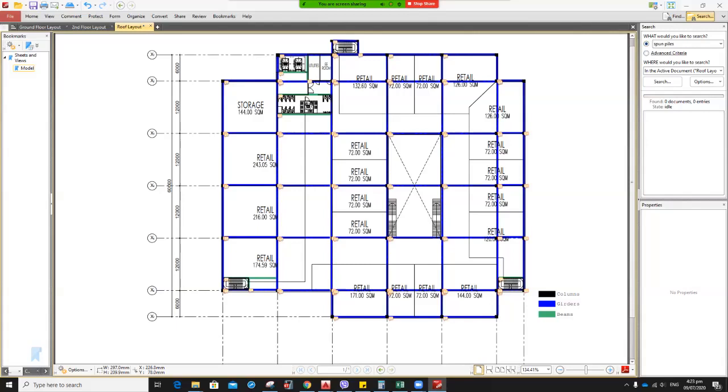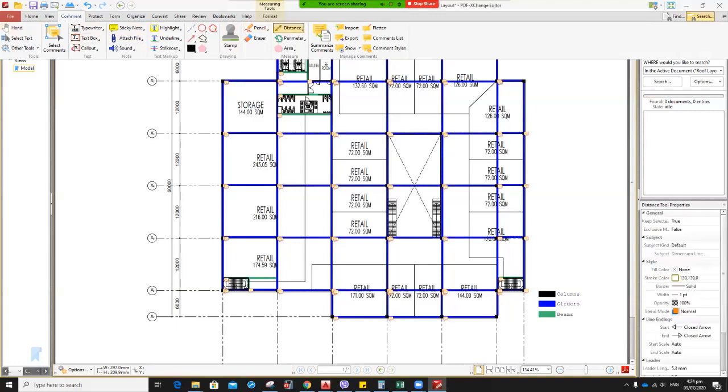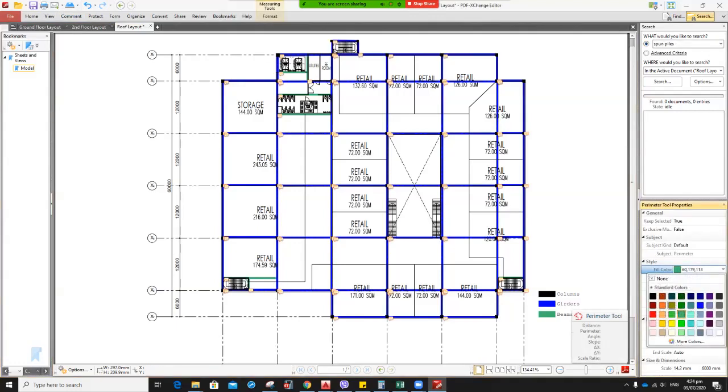And then we will just show the loading from the roof. So how are we going to do that? We just need to conceptualize one frame. So we will have truss along this one, and then we will have the purlins going there. Okay. So we will have trusses here. I'll put it in red, the trusses.